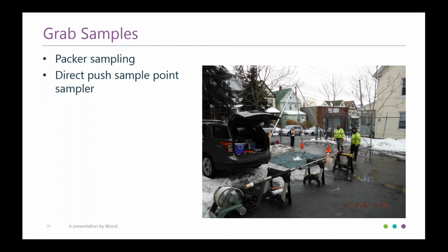And then we have sample point samplers. You're collecting your soil samples, the screen's there, they pull back and the screen's exposed, and you can collect a groundwater sample as you're doing that. Again, it's not equilibrated. You're not making sure that your parameters are all stabilized. But if you're evaluating a large area and as you're going, you just want some general information about where contamination is, where it isn't, or set a well, okay, at the end, we're at the extent, let's set it 10 feet beyond here as a monitoring point. It gives you some information.